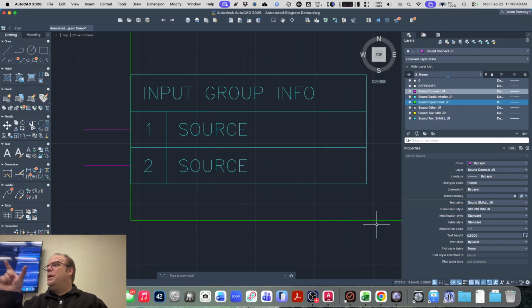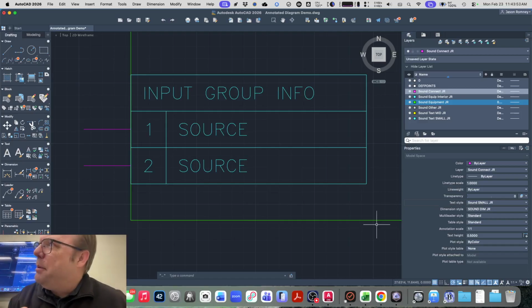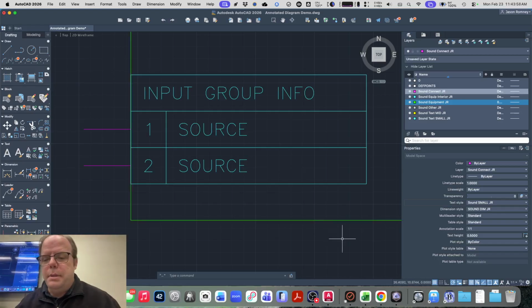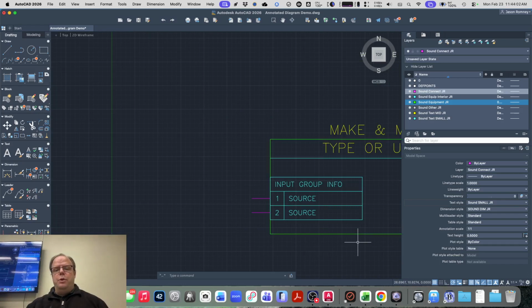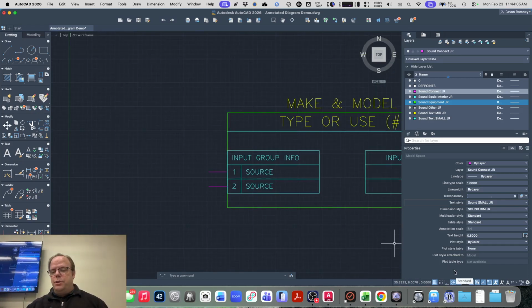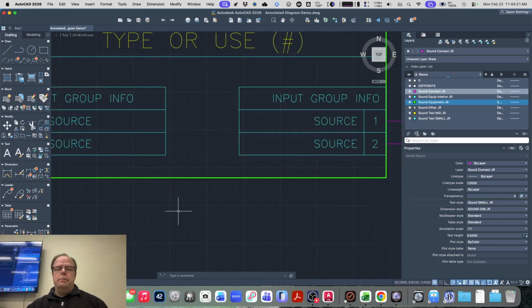That way those lines will always be a little bit thicker, and I'll not have to worry about that overlapping line rendering problem because those lines will be thicker anyway, and it won't be a big deal. And that line weight only shows up usually when you go out and print it. If you want to make sure you've done it, you can turn on here at the bottom the show/hide line weight thing, and you should see that line be thicker, just to make sure you've done it right. I usually don't like to have those turned on when I'm drafting, but if you just want to make sure you've done it right, then you'll know.